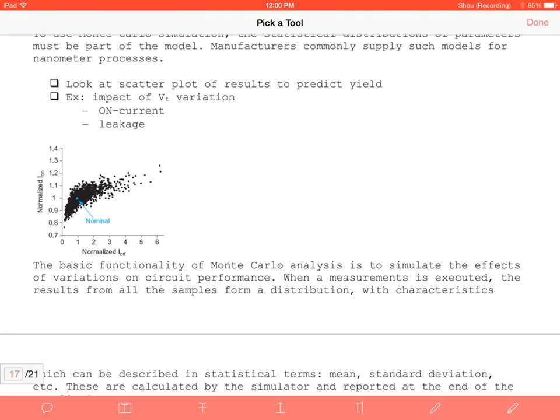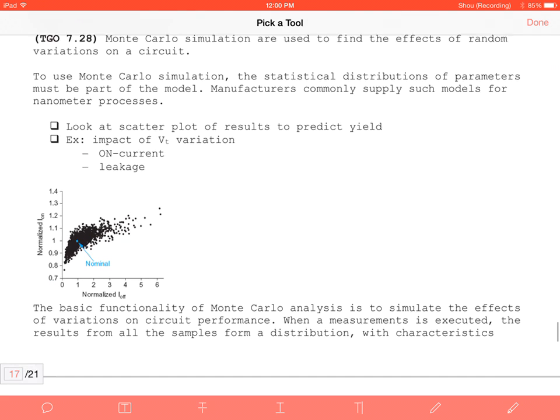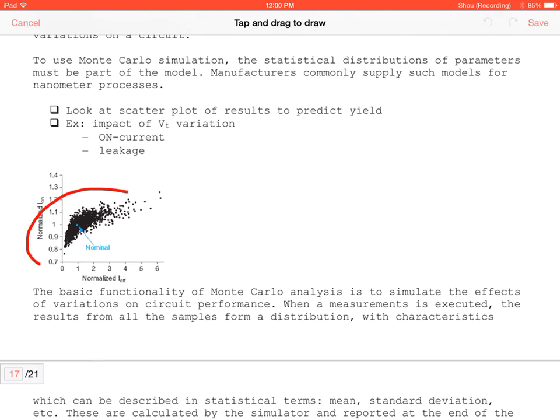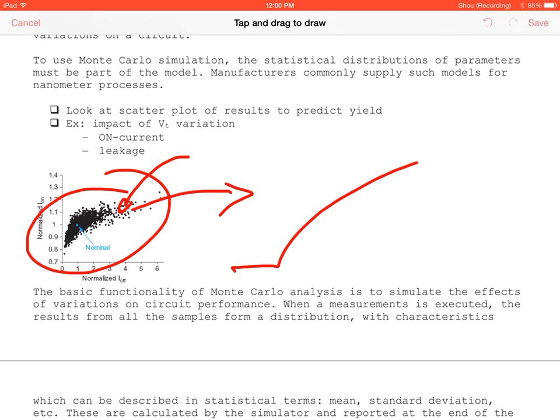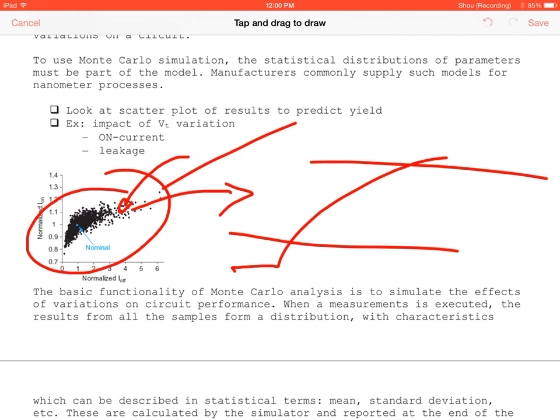I'm going to present 4 different ones that we can do. And we want to simulate the effects on circuit performance to see if it still works. So if we have a circuit that tests out here, and based on that we figure out that we have terrible rise or fall times, or we aren't able to consistently reach the noise margins, that's when you're going to throw out the chip.